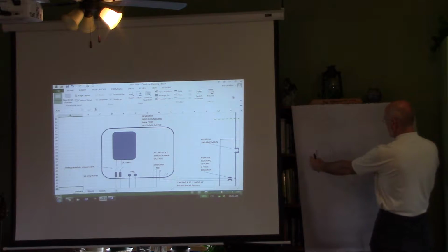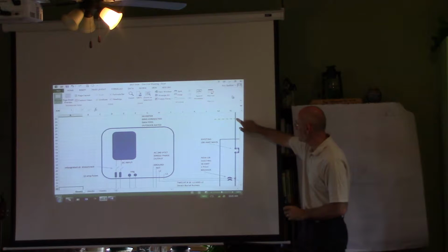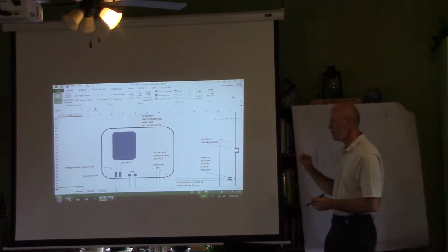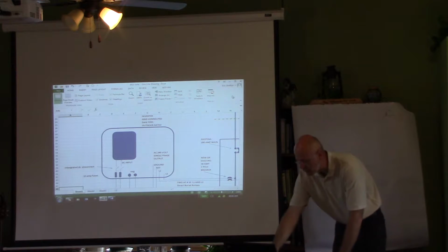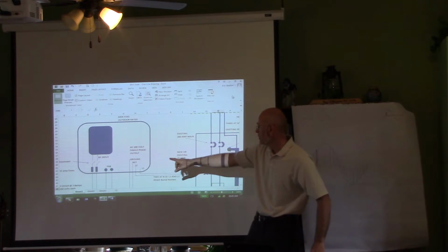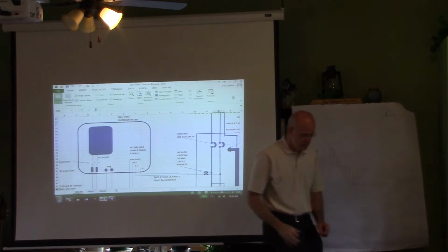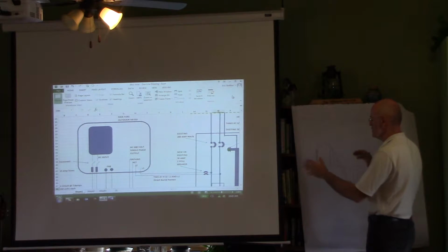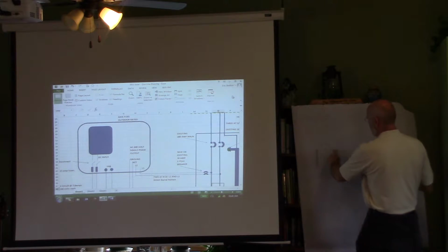And when that pattern produced by the inverter matches the utility's pattern, and they're in time, the transistors close and they connect. See where I can do that. Internal to here, it has the utility side, and then over here is the inverter. It connects them with the transistors and says, okay, I'm happy. I can see the utility, I can see the DC, they're in phase, I can produce the same waveform. Okay. Now here comes the magic.